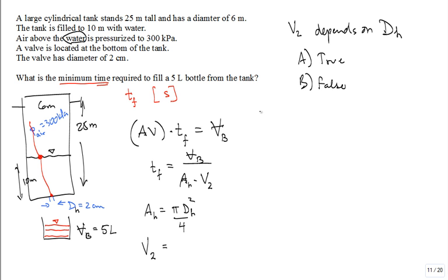What do we have? We have the pressure at 1. There's negligible velocity at 1 because it's a large diameter tank. Plus rho g times H, which I'm just going to call the height of the water level. It's 10 meters above the hole. H is 10 meters. That equals the pressure at the exit, which is atmospheric pressure, P2, then plus 1/2 rho of the water, V2 exit.